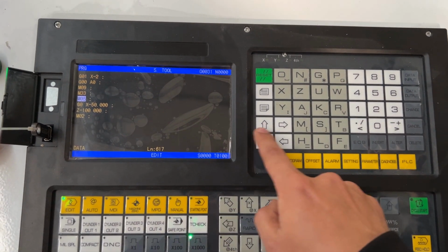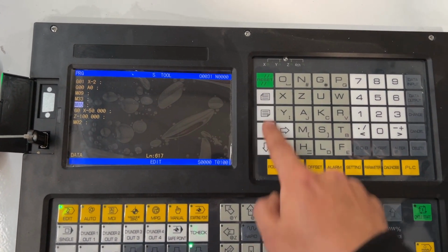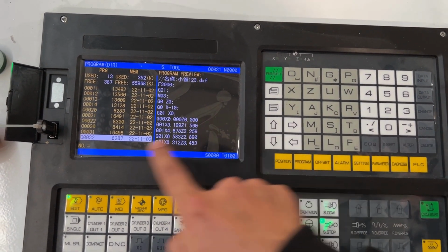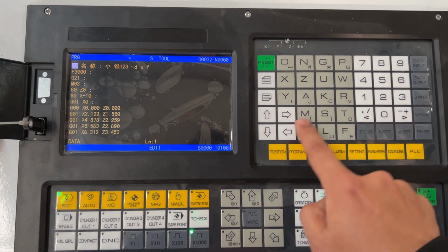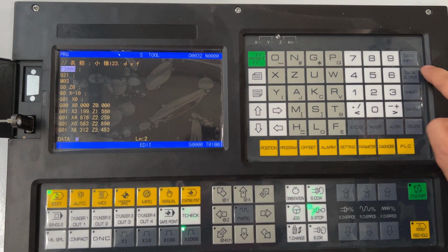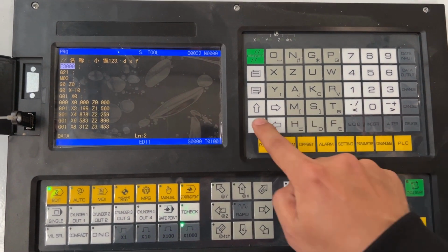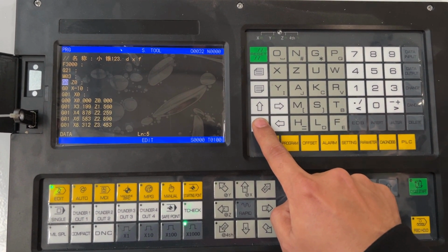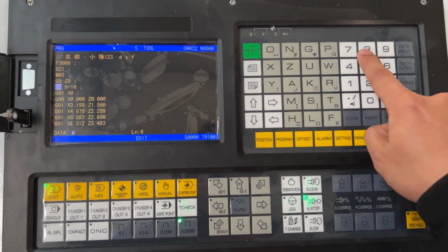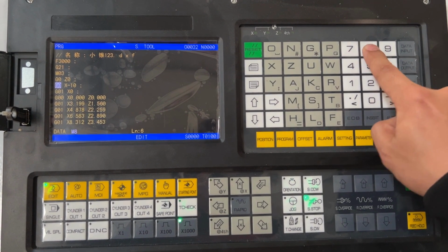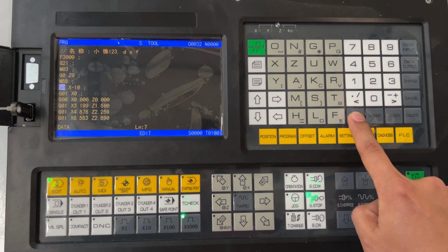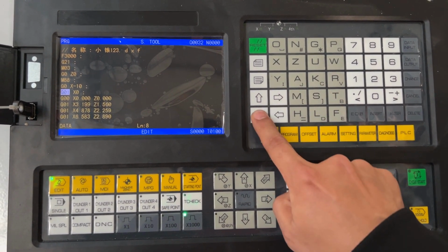After program editing is complete, press reset. Return to program start position. Continue editing the grinding wheel program, file 32. This one also can't pop up for now. At the Z0 position, input M88. Add the grinding wheel pop-up code below G0Z0. The machine model is different, the code is different.